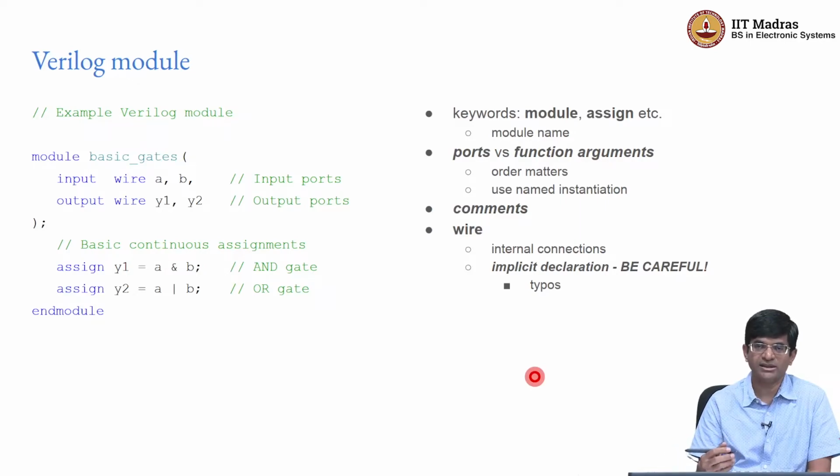Every module, rather than thinking of it as a function that can be called, it is much better to think of it as a chip on a breadboard that's connected up through wires to various other chips and is always active, which means that whenever any of its inputs changes, potentially I'll need to go in and see what happened inside the module as a result of the changes at its inputs. And as a result, it might end up changing its outputs, which in turn will influence other chips that are connected on the breadboard or other modules that are connected in your Verilog code.